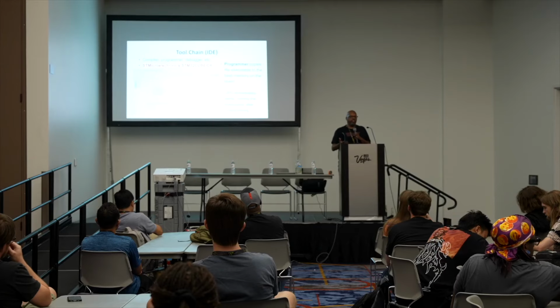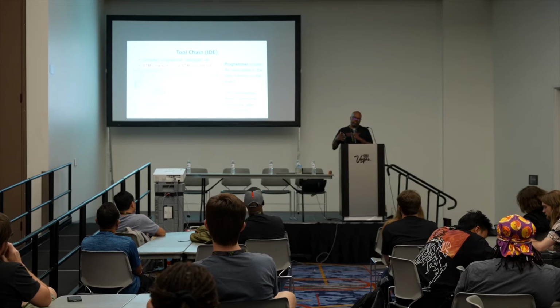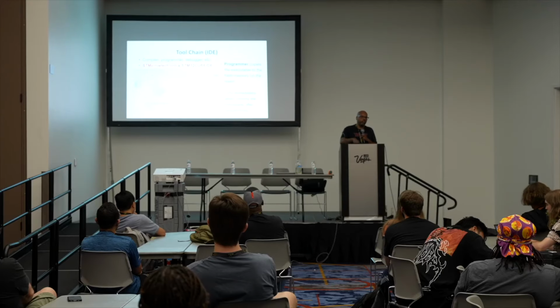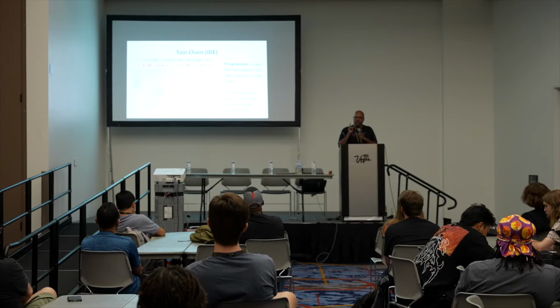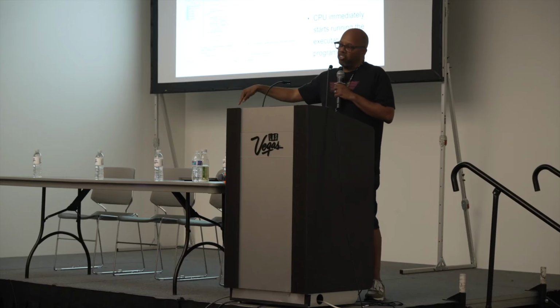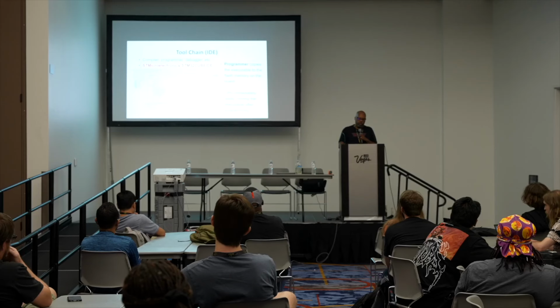So the one difference in an embedded system IDE is that you have a programmer that's attached to it. Once you compile the code, you actually cross-compile the code. Normally if I compile code on this machine, it'll be compiled to execute on this machine, on this microprocessor. But with an embedded system, you compile it on this machine to run on a different processor, right? That's called a cross-compiler. So this thing uses a cross-compiler, and the last step is to take the cross-compiled executable and program it into the flash of the actual device. And that's what a programmer does.